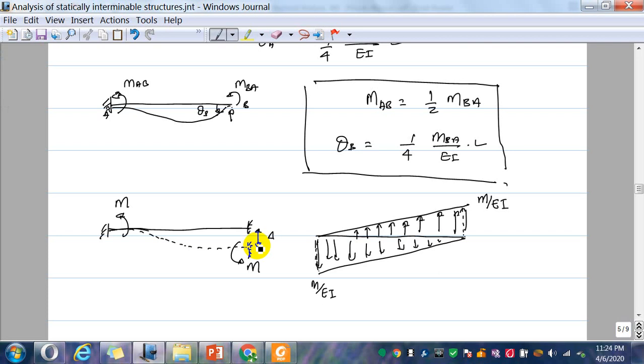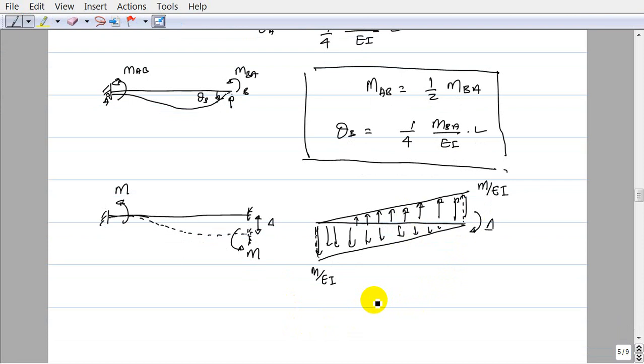So if the deflection is downward, negative, then we need to have a bending moment, a negative moment. Negative moment means it's clockwise, so delta, because counterclockwise is positive. Okay, so this is the conjugate beam for the real beam with the settlement.